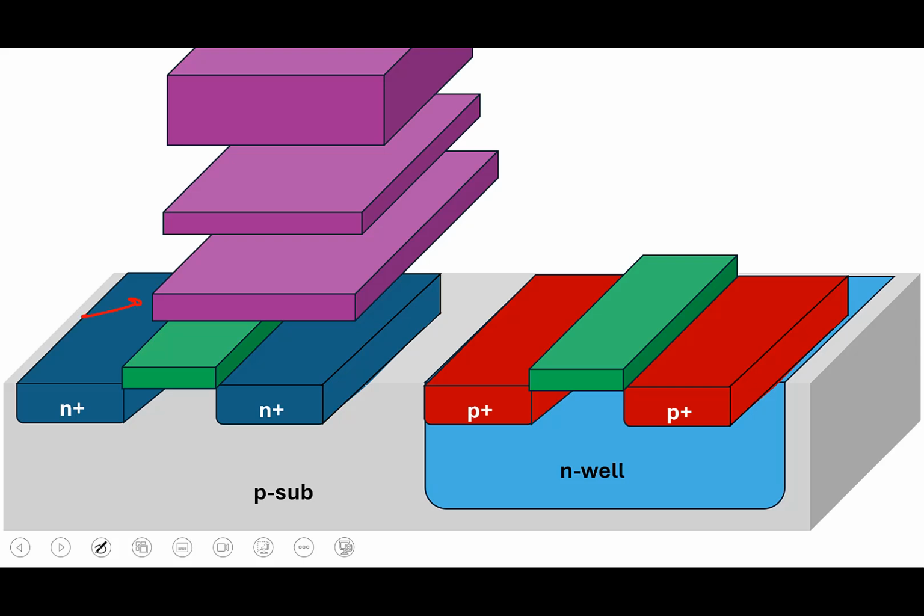So we'll have multiple copper metals like this at multiple levels, so that you can have different options for connecting. Since here I could draw only 3, I have drawn 3. But in modern processes, you can have 8, 9, 10, 12 or anything. Different copper metal layers, everything is available for connection. And sometimes in some modern processes, you might have at the top level an aluminium metal like you guys mentioned. And that will also be a thicker metal, so that resistance is much smaller. But it might not be available in all processes.